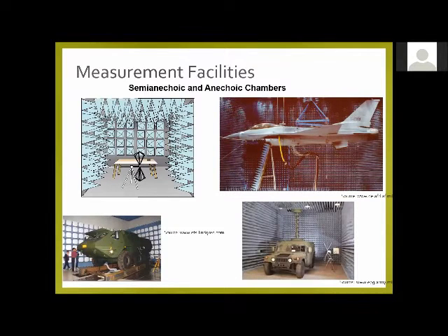The next thing that we have is semi-anechoic and anechoic chambers. These are best if you start in a reverberation chamber and then you move to a semi-anechoic or anechoic chamber. And you can exactly figure out what polarization and frequency you're looking at and where the problem is.